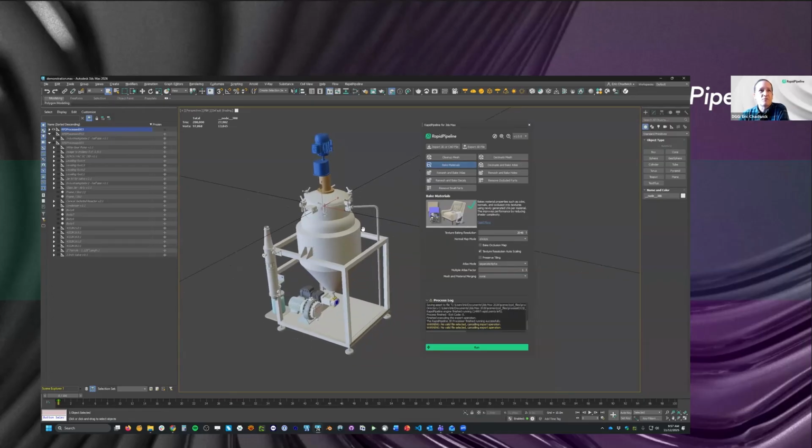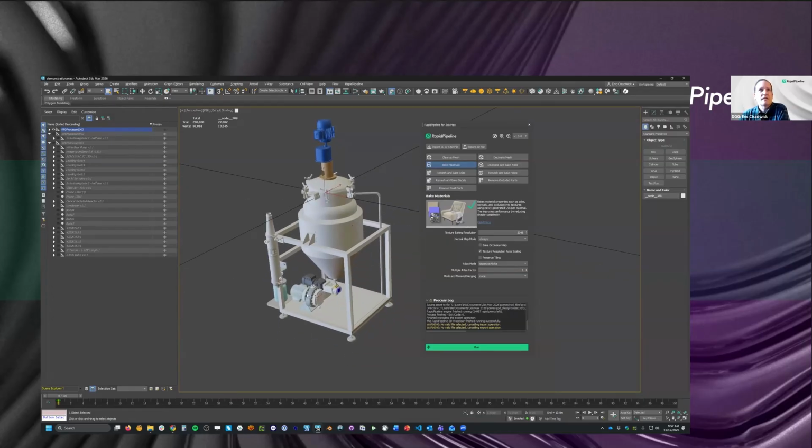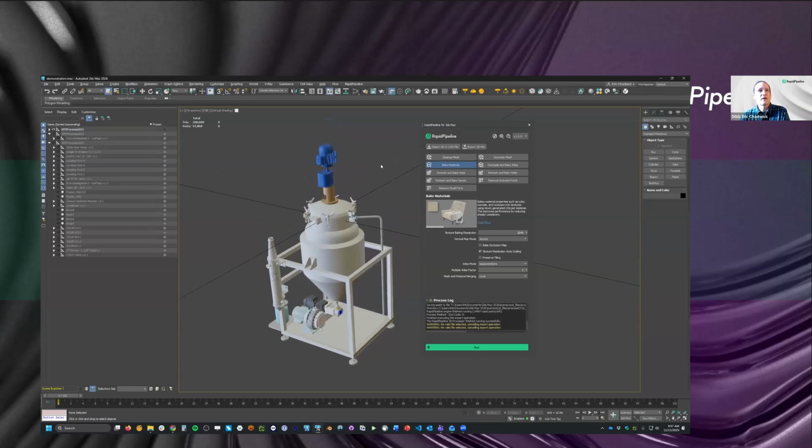That's really helpful when you have a super complex asset like this. And say you want to decimate these parts down to a lower ratio than, say, the other parts. You can just select which asset you want to apply, and the actions are applied only to the selected objects. So that's what's super useful here, but it's not really meant for kind of a batch system.